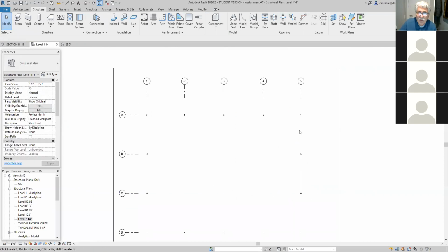In other words, for you guys to understand structural steel, when we're talking about a wide flange, this here is called the strong axis and this is called the weak axis, and therefore you have to make sure that the flanges are in a certain orientation because, for example, if the wind is blowing this way, you want to make sure the strong axes are resisting that wind load and so on. So that's why it's very important in structural steel in which orientation we put the columns as well as the beams.